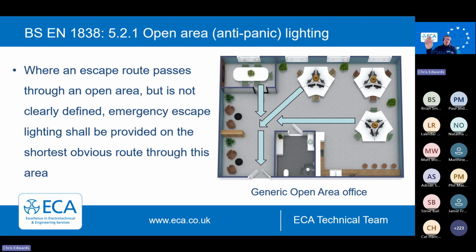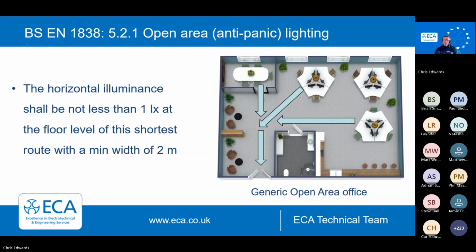Open area is generically half a lux. Escape route lighting would be 1 lux. But that's down to the design and down to the risk assessment when you're looking through these items.